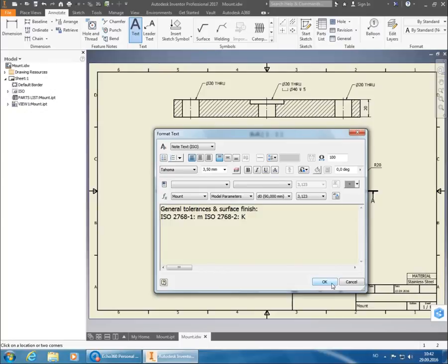So you just placed in something because you didn't know, you didn't have it specified in the submission, so you put it after your best knowledge. So that was very good to do. So that counts also towards the next 2 submissions. If there is some information you feel that you're missing, then it is better to actually assume what it is, so that if you haven't gotten any tolerances set or anything like that, then you just put in something that you feel. My recommendation would be to use the medium ones, which are very often used in machining. So it is a very safe bet to use when you're putting them in. And also for material, just choose something that's appropriate or gold.